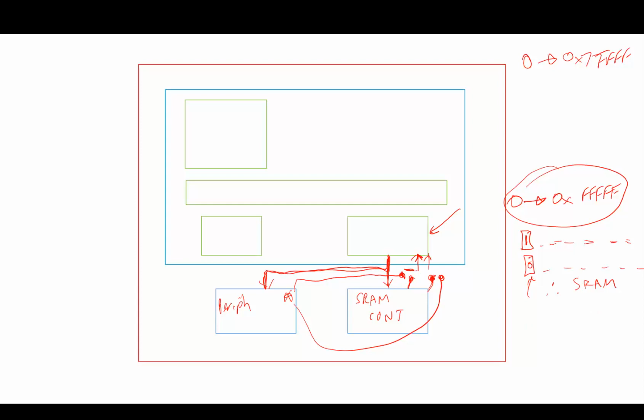If the upper bit is a 1, then you should be accessing the peripheral signals. So you should just have simple conditional statements in your top level module for part 3 that implement this switch functionality for those signals. The other signals are just duplicated to send to each of these modules.